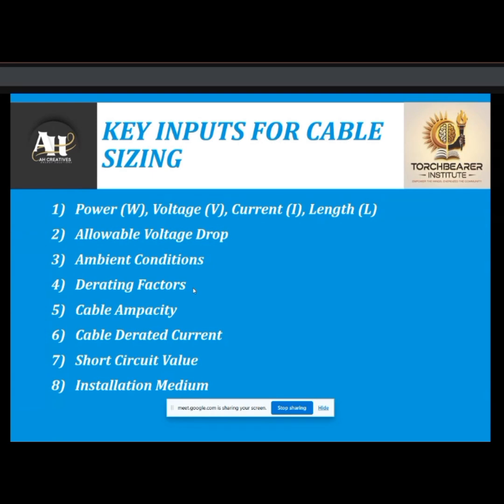The manufacturer has given us the short circuit value of the current which can apply to the cables, and the cable has to bear this short circuit. On that basis, we will calculate the short circuit value of the power plant and then apply it on the cables. If the cable satisfies this criteria, we will consider the size of that cable.